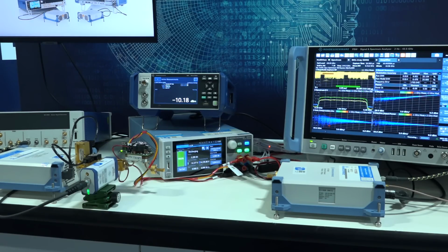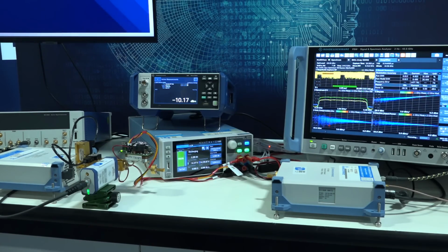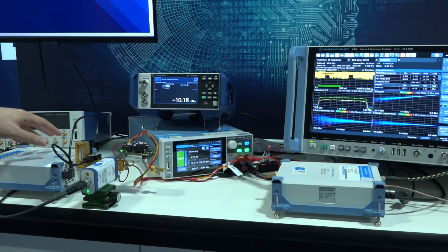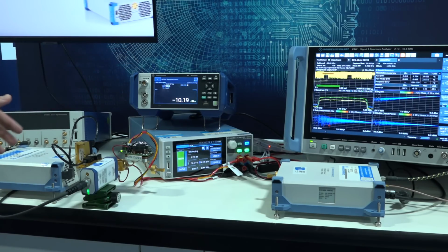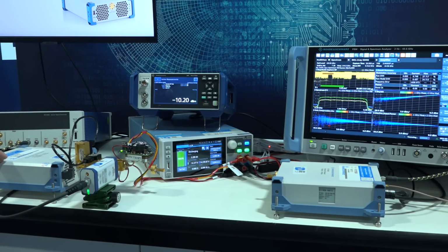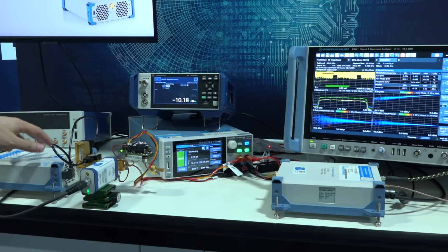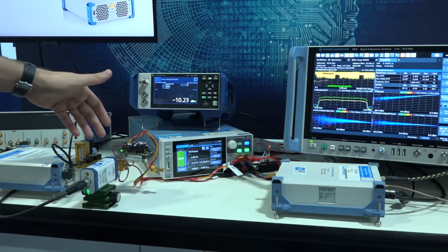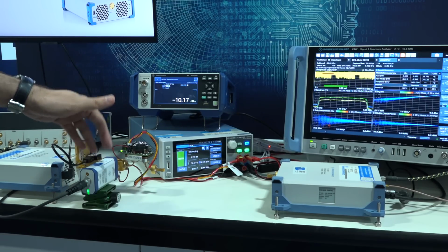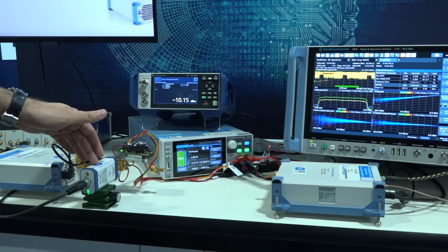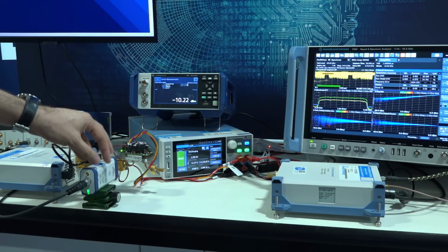And here we have a live wireless demo between 110 to 170 gigahertz. It's using the FE170, which I've done an extensive review on the channel. This is a fairly complex setup. A lot is happening at the same time. So we have the FE170 as a transmitter gear with its pre-select filter in the front, which is automatically embedded inside the software. And then we have a coupler over here connected to the thermal power detector between 110 to 170 gigahertz. This itself is unique in the world.